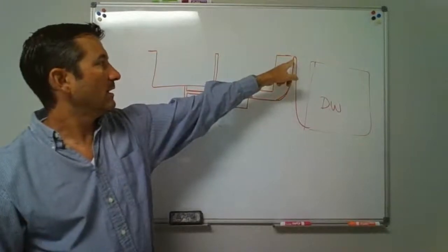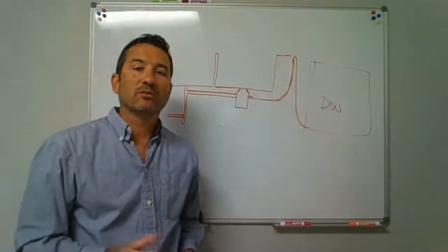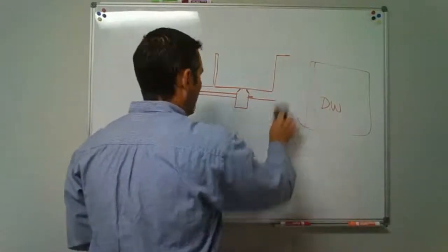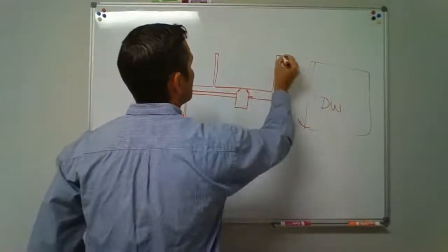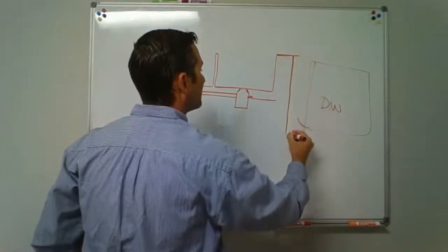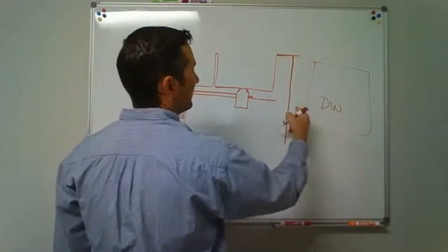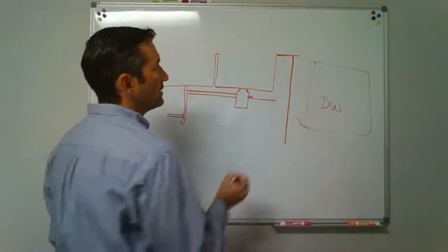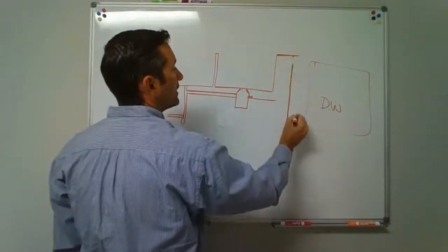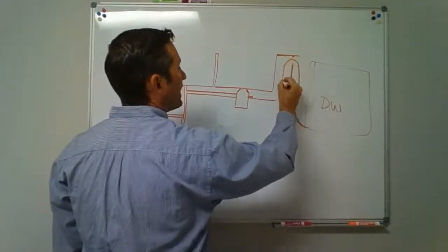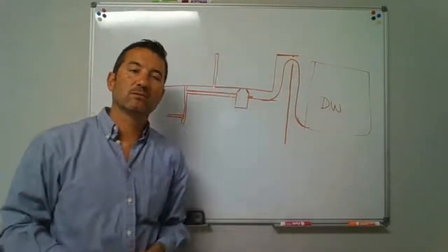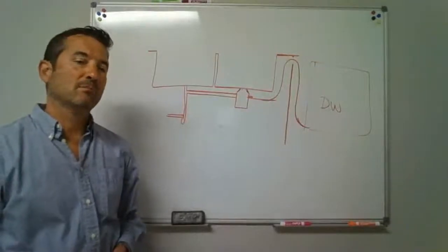And now I normally don't take some type of clamp or anything and try to hook it to the bottom. What I do is normally you've got the kitchen countertop here. These cabinet pieces came in, and there's going to be a wall to the cabinet right here. Okay, and we slid our dishwasher in this opening. It's on the other side of the wall of the cabinet. So I drill a hole right there at the top where my dishwasher is going to go and feed through the hole of the cabinet and then back down in. And this cabinet wall is holding the dishwasher drain up, and that meets that rule.